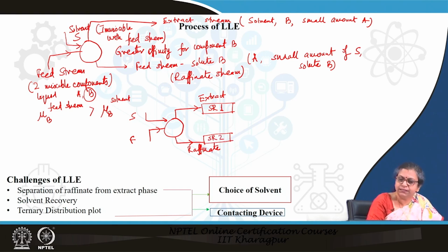Generally, the process normally in industries is that we undergo a flash distillation, maybe two flash distillations, one under pressure and one under vacuum, and after that, if required, we go for steam stripping or a distillation. From here, what do we get? We get the extract E', from which the solvent has been recovered, depleted of the solvent.